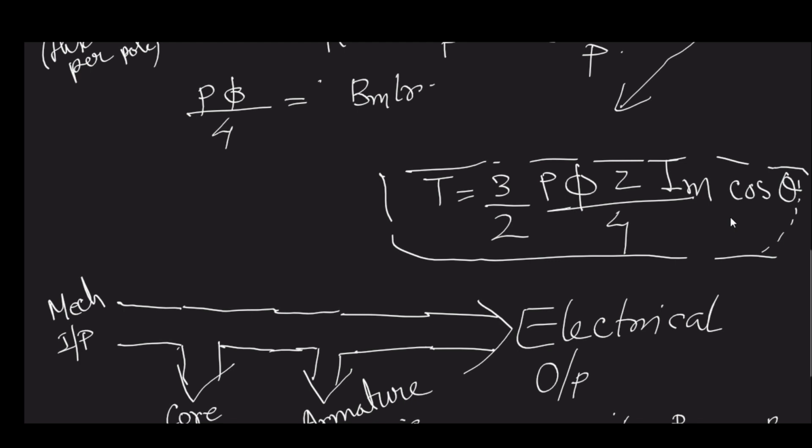it may happen that if you can generate a stronger pull, then even if you withdraw the mechanical power that you are providing through your prime mover, the electromagnetic pull may be so strong that it can allow your rotor to continue at a synchronous speed.